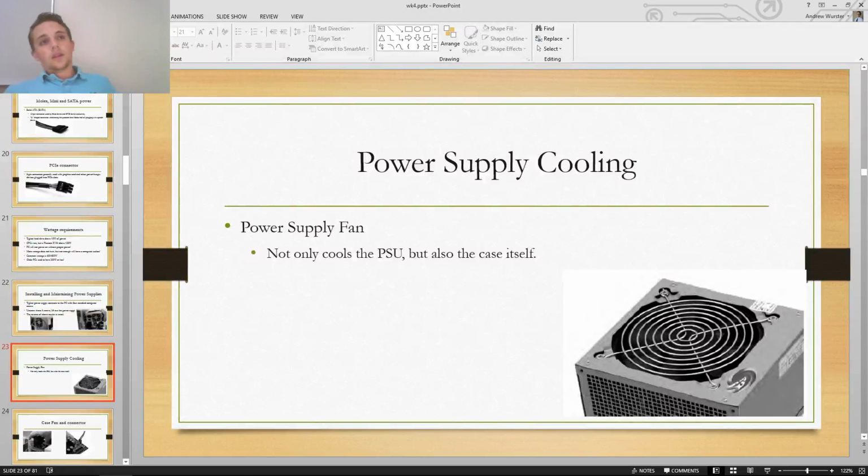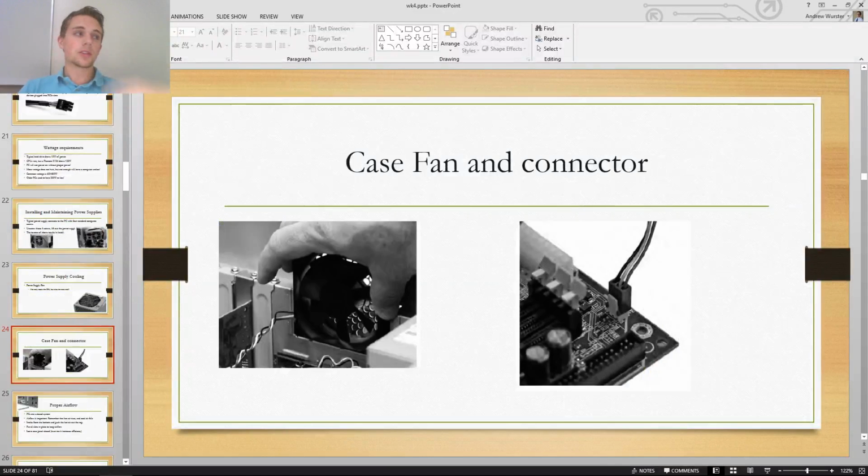You can either do it that way, or you can say in that range, I want the fans to go at a maximum of 80%. If you have smaller fans, it's going to be like a jet taking off. The bigger the fan blades that you get, the quieter it will be, and the more air it will physically move. So it'll be more efficient, but you have to have the case to be able to support that. Like this one, this is a smaller 80 millimeter fan, so they're measured in millimeters. Some of the bigger ones are 120 millimeters. Those are a lot quieter.